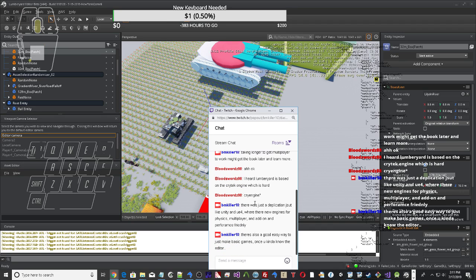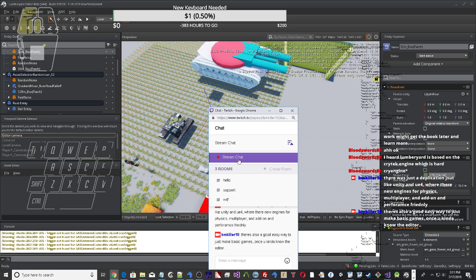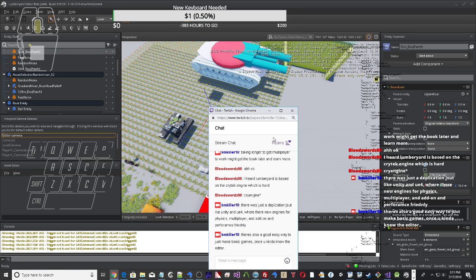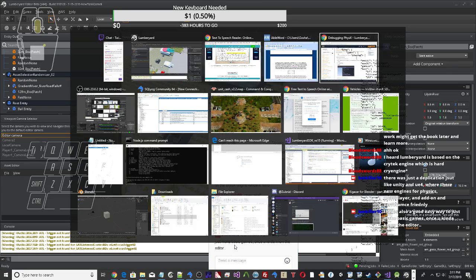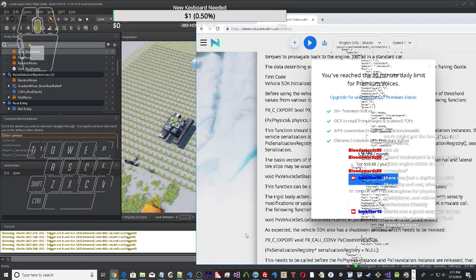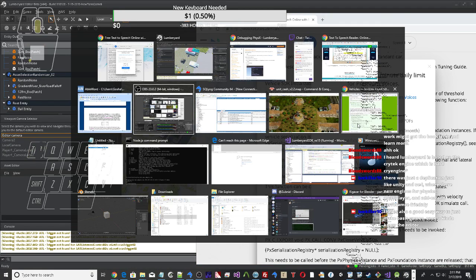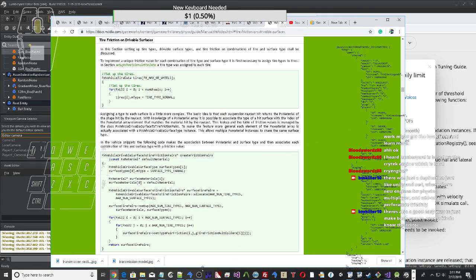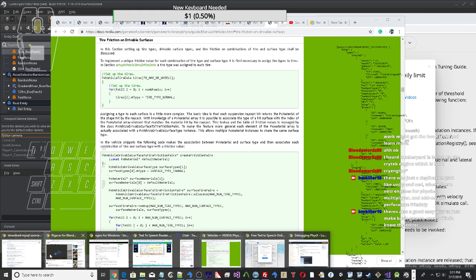Under ordinary circumstances, the effective radius will be no more than a few percent less than the unloaded radius, and the RPMs should be, then, a few percent more than 129 rpm per 10 miles per hour. At 100 miles per hour, the tire is under considerable stress and spins at something over 1,300 rpm.